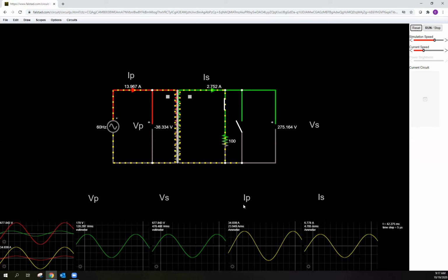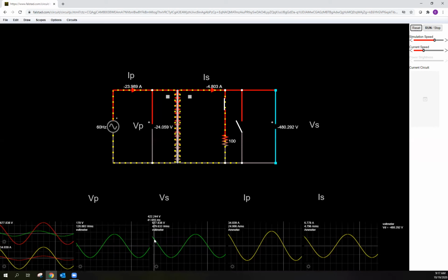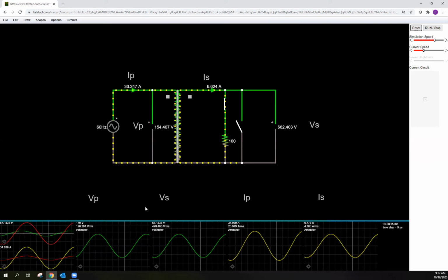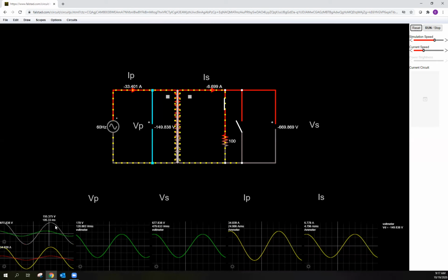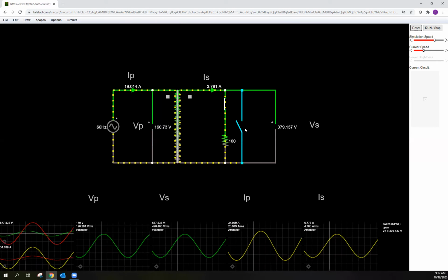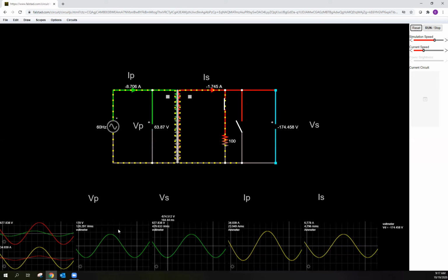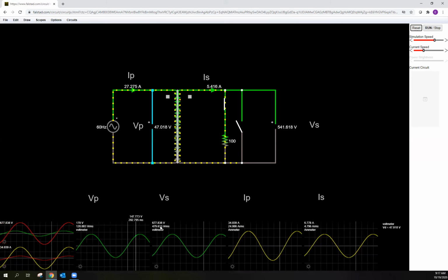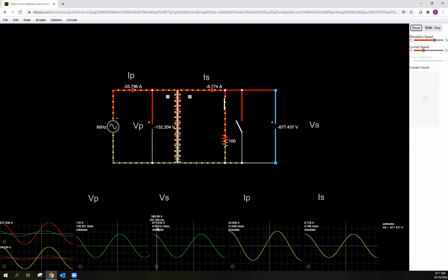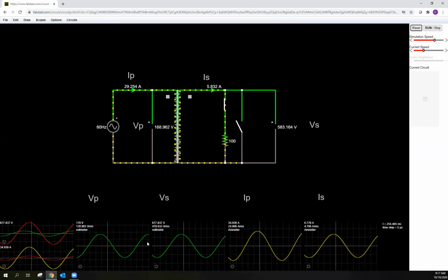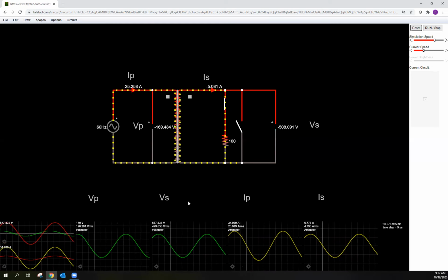Do we still see a nice result? It looks kind of okay, right? You can see that the voltage of the secondary does increase, but it doesn't increase exactly 5 times, because 120 times 5 is not 480, it's 600, right? Okay, so you're seeing it's trying, but not quite perfect, right?